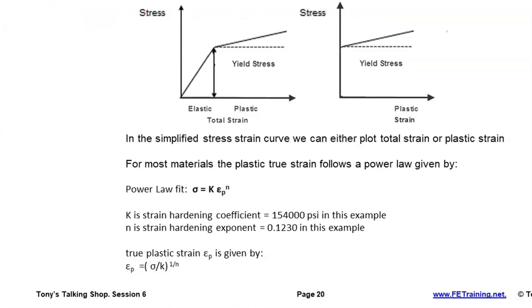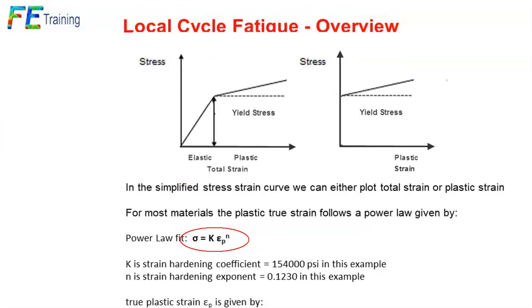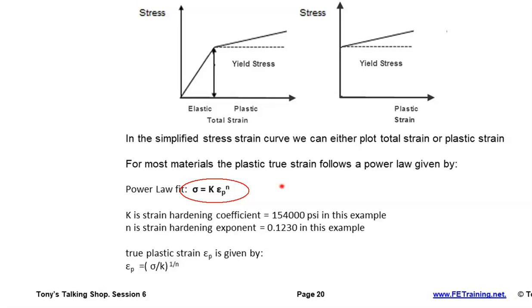And the power law is useful because then plasticity will be a continuous slope, which might fit our data better. And again, I've got 2 more coefficients to deal with, the strain hardening coefficient and the strain hardening exponent. So I've got a way I can actually mathematically draw that curve and deal with that. So that's the approach that we take in there. So that's our material law, given by that particular stress strain curve.